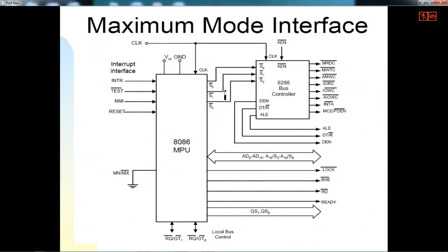So now you can see the same thing here. This is your 8086, and when the 33rd pin is connected to ground, it is in maximum mode. Then you can use your S0, S1, S2. This is the same thing, but in a clearer manner. So from S0, S1 and S2 you can generate these signals using the 8288, and then you can generate data transmit, data enable and ALE equivalent signals, which you can connect to memory. For address demultiplexing, and also for buffers and latches, you can connect these three signals. That's what we clearly saw in our last class.